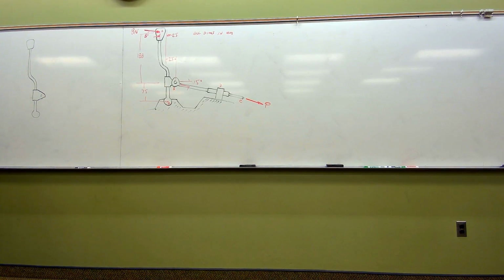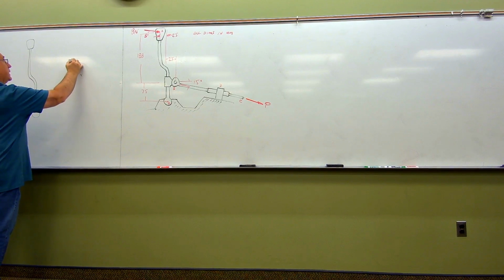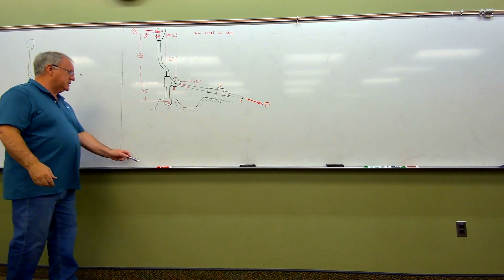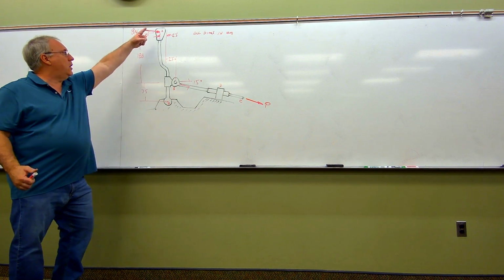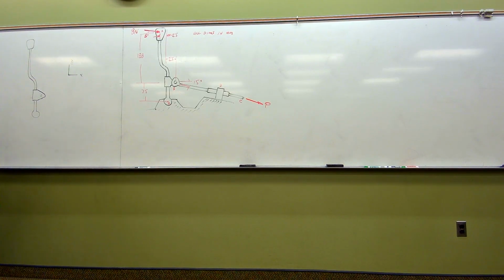Okay, now with that, let's complete our free body diagram. So we've made our sketch, everything's isolated, there's no ghost lines touching or anything like that. I'm going to use a standard X and Y coordinate axis system on this one, folks. Let's start with, were we told anything at all about the weight of the shifter arm? No. Therefore, we don't need to worry about its weight. We do have an applied force up here of 8 kilonewtons, or I'm sorry, 8 newtons, not kilonewtons, 8 newtons. Same 5-degree angle right here. Got that. So that's applied. Again, no weight.